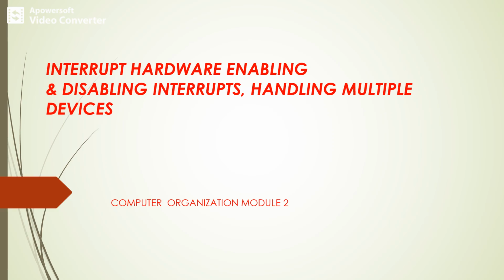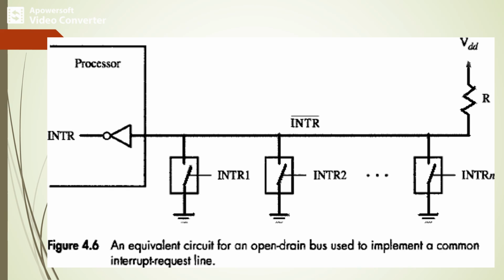In the present video lecture, we'll discuss interrupt hardware, enabling and disabling of interrupts, and handling multiple devices. First we'll consider interrupt hardware. The diagram shows an equivalent circuit for an open drain bus used to implement a common interrupt request line.